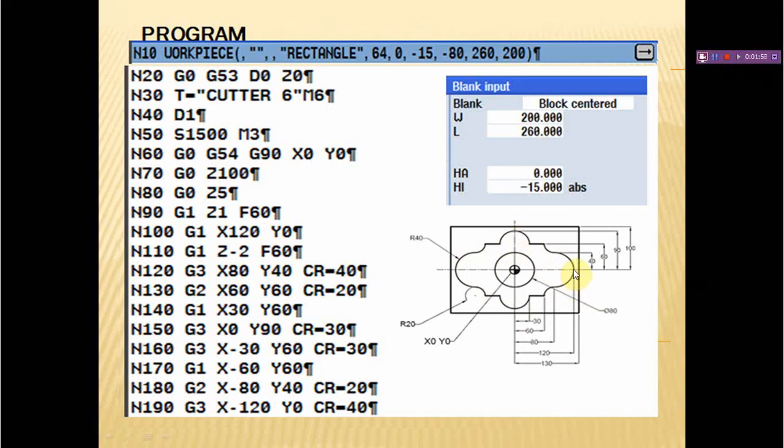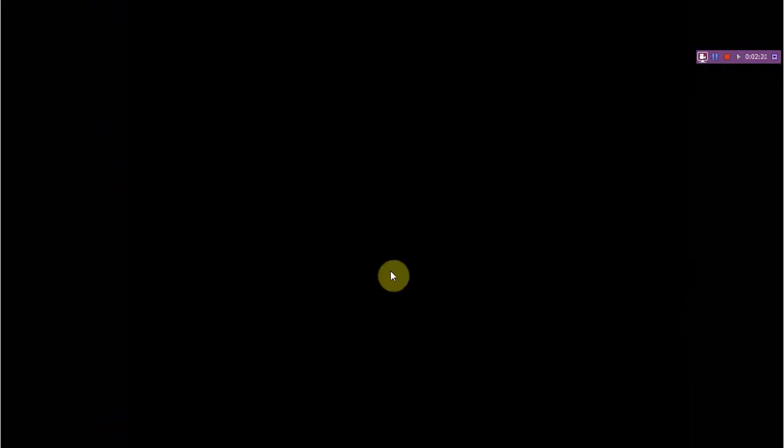After this, simply lift the cutter to surface level and then position the cutter at this point. Once again give depth of cut. Just to rotate the cutter, we will get the circle. After that, lifting the cutter, go back to reference point, switching off the spindle and then put M30. The program will be over.